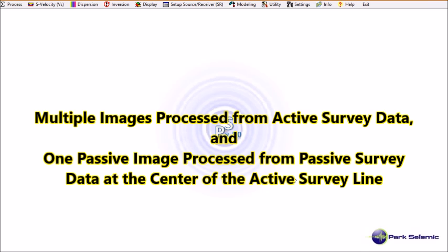I'm going to demonstrate how to combine one passive dispersion image into multiple active dispersion images. For example, you have an active dataset collected through the conventional roll-along approach for the purpose of generating a 2D velocity cross-section at the end. And during the active survey, you performed a passive survey approximately at the center of the survey line by using preferably a larger dimension receiver array, which is preferably a two-dimensional receiver array.